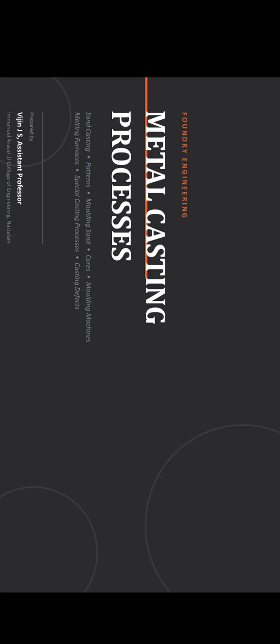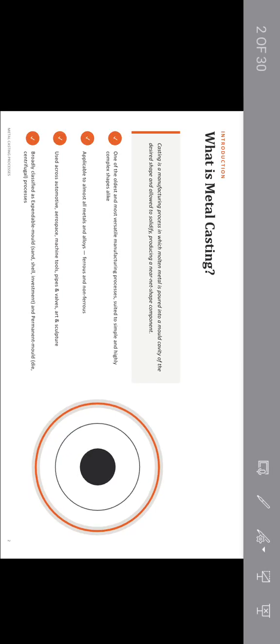Metal casting process. What is metal casting? It is one of the oldest manufacturing processes, suited to simple and highly complex shapes, applicable to almost all metals and alloys, ferrous and non-ferrous, used across automotive, aerospace, machines, tools, pipes, and valves. Broadly classified as expendable mold (sand, shell, investment) and permanent mold (die, centrifugal) processes.